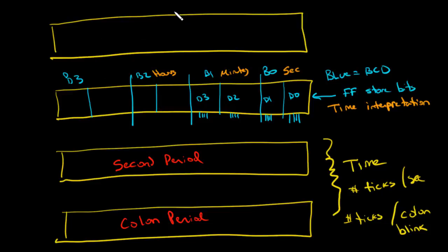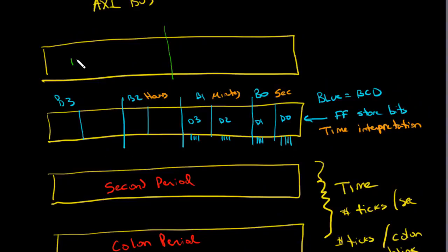So if I do the bitmap mode, I know that I need 15 bits to store all of those values. And so, for instance, I could use up here in this register 0 the most significant 15 bits, and then those 15 wires would go down directly to drive the cathodes and the anodes. So by writing a value here, I could set whatever values I wanted to set. Just like if I write a value into here, I could set a value into the BCD input to the BCD controller.